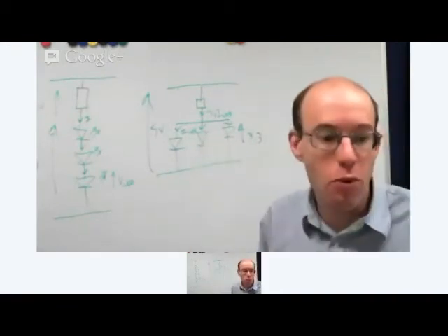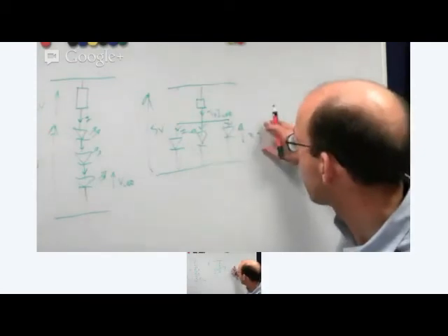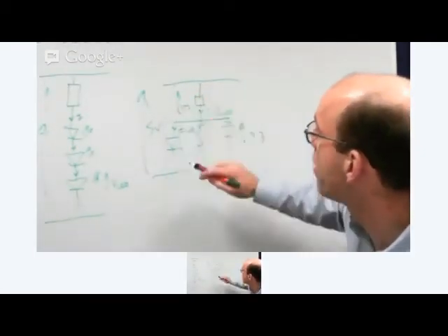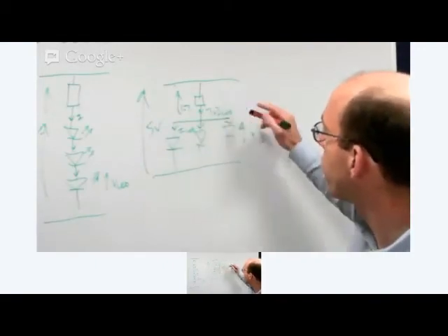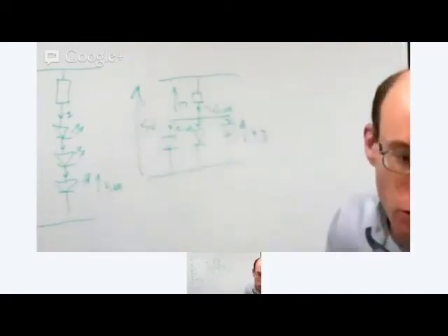So that's why I'm saying it's important to make sure that they are the same. And then we can do the same maths again. If we've got 3.3 volts there, we've got 1.7 volts there, and the current there, if it was going to be 10 milliamps, it's now 30 milliamps, and we can do the maths.